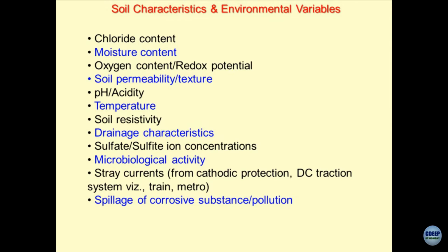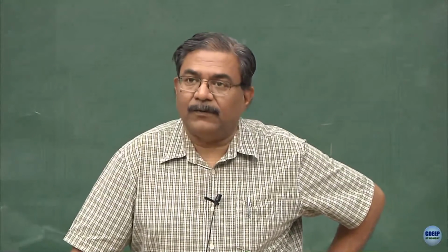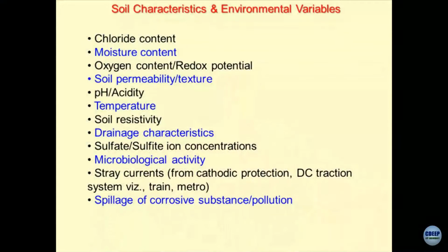Or this may happen because of an act of God, or because of an act of human beings. You have a storage facility somewhere where a lot of contaminants have been stored and they are leaking, and all this leaking material is entering the foundation pit, and if the pH changes, what type of alterations in the bearing capacity and the compressibility of the soils are going to occur is a big question which we are trying to address. Temperature.